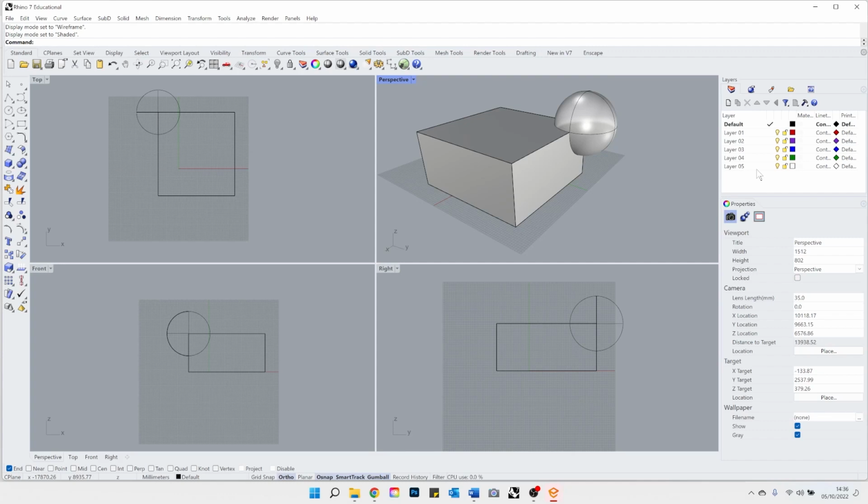Again, if you have 10, maybe 20 objects, it's fine. It's not too big of a deal. If you're working on a master plan, or if you have enormous skyscrapers that you're designing, you will not want to do that later on, okay? So just learning from the beginning, start using your layers. Layers are really straightforward in Rhino.